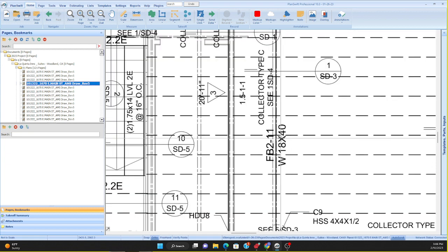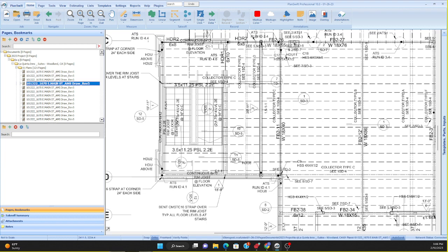And so we know that the last digit of that indicates how many pounds per linear foot the beam can hold. And so when you're doing your takeoff, right, you measure how many linear feet you have, and you know how many pounds per linear foot, then you can determine how many pounds that beam is, because fabricated metals are priced by the pound. Okay, and so that is a gem of a tip, and never forget.